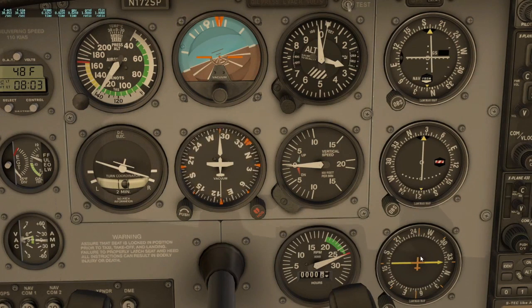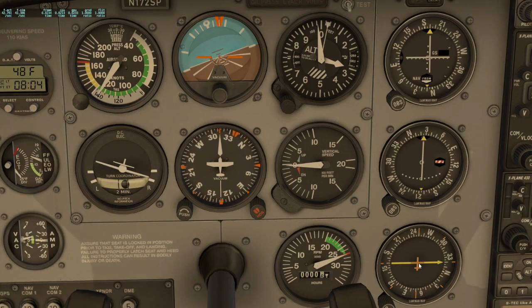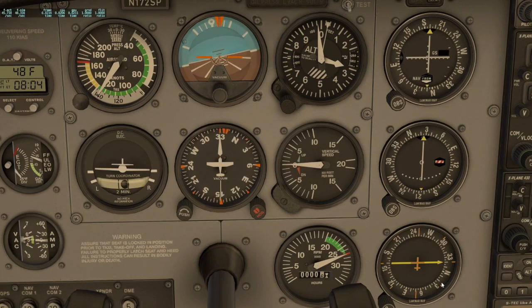So I intercepted this guy. Now I'm going this way until I'm 30 degrees from 250. That's 220, and then I'm gonna go 45-degree angle to intercept this guy inbound. What is 45 degrees this way? Don't need to do any math whatsoever. Here we go. It's direction 025. 025 is coming this way.